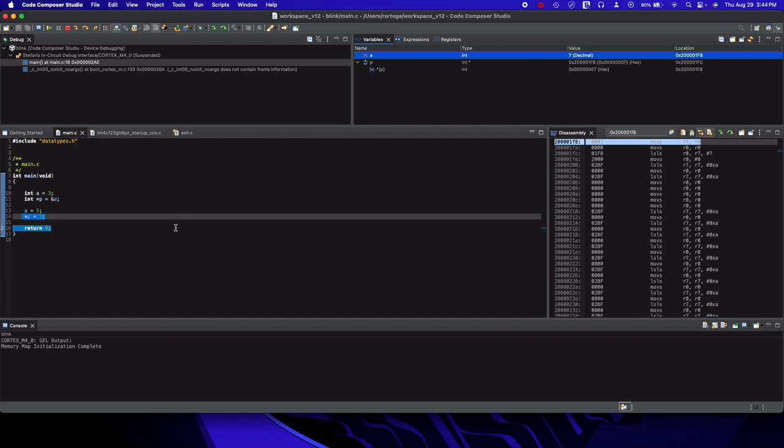This is very useful because we're going to see later when we want to modify a register, let's say peripherals. We want to modify a port to set an LED, or we want to read some switch that we have connected in one of our inputs. We can read directly and we can modify directly the memory address of that register. By doing so, we are manipulating the peripherals of our microcontrollers.